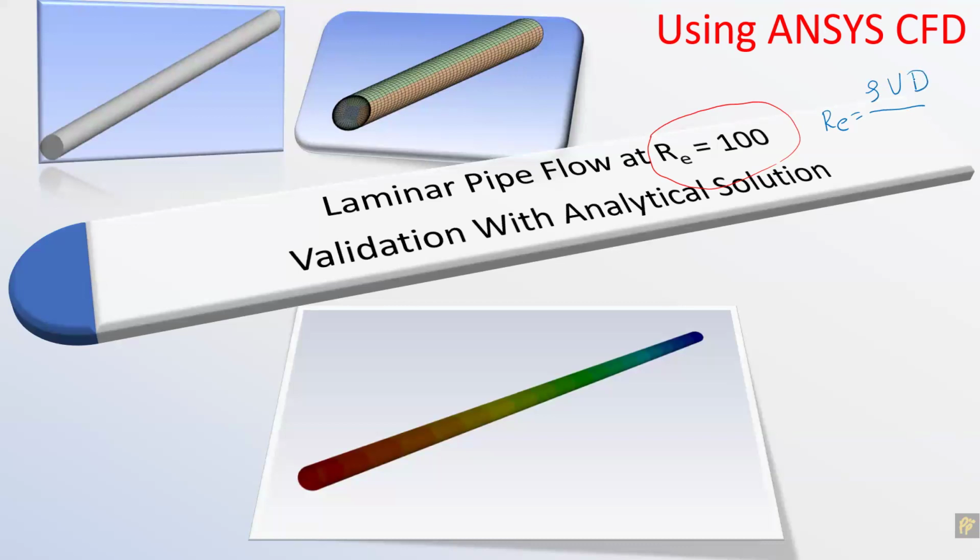This dimension is basically the characteristic length of the flow. This characteristic length can be the diameter in a pipe. This can be a length, for example, chord length. For a combustion chamber, this can be the diameter of the primary holes, secondary holes, tertiary holes. Depending on which dimension is going to affect the flow most, that dimension will be used over here. And this is divided by the viscosity.